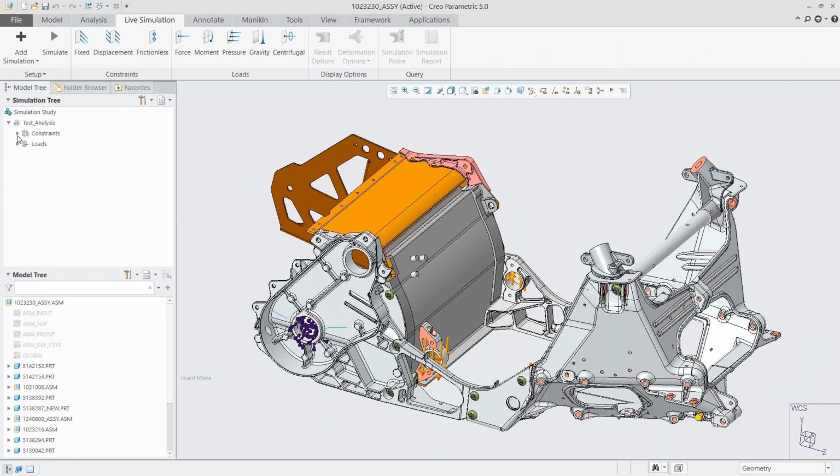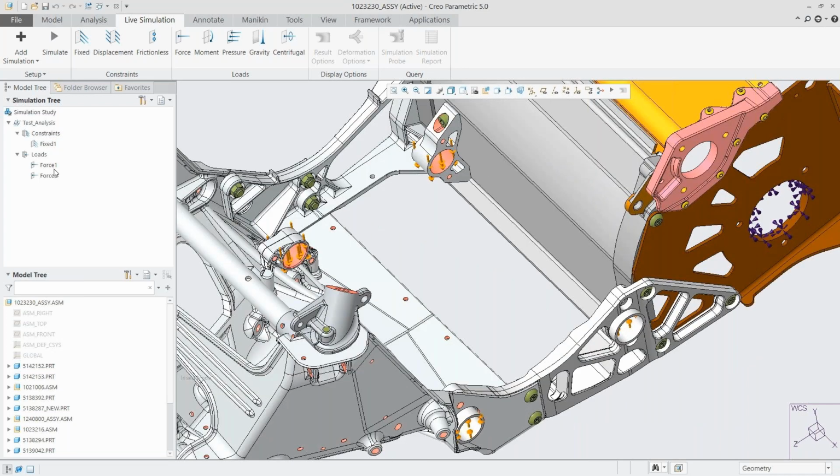So this is going to start in the same way that we laid out some constraints earlier. So we have our fixed surfaces. We know that we don't want those to move around. And this is, again, with this whole assembly. And I know maybe whenever I put in another part here, I'm going to have some forces being applied. And maybe if it's shaking around, we're going to have a downwards force on the right, and then it's going to have a resulting upwards force on the left. So now that we have this laid out, let's go through and run our simulation.